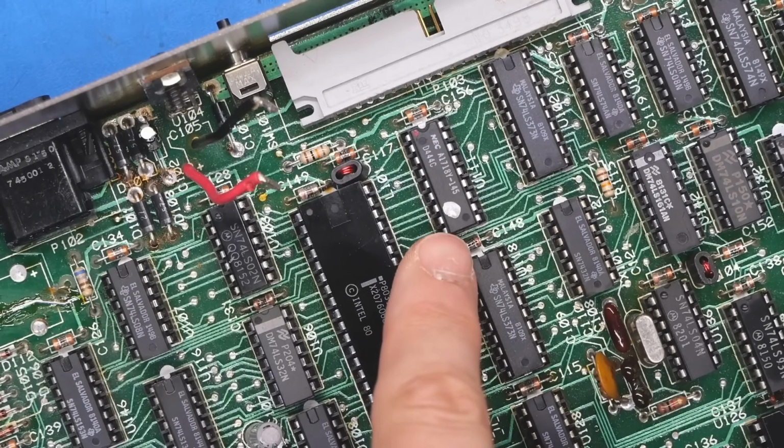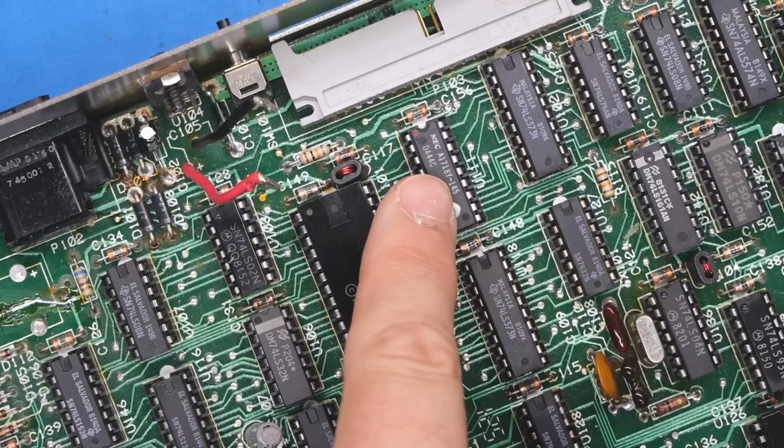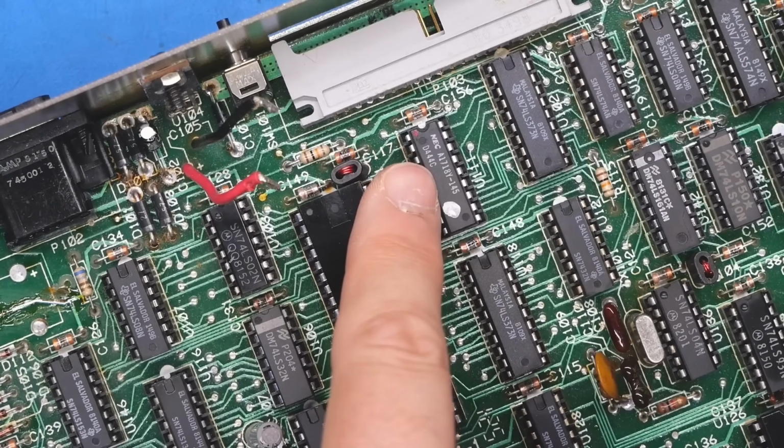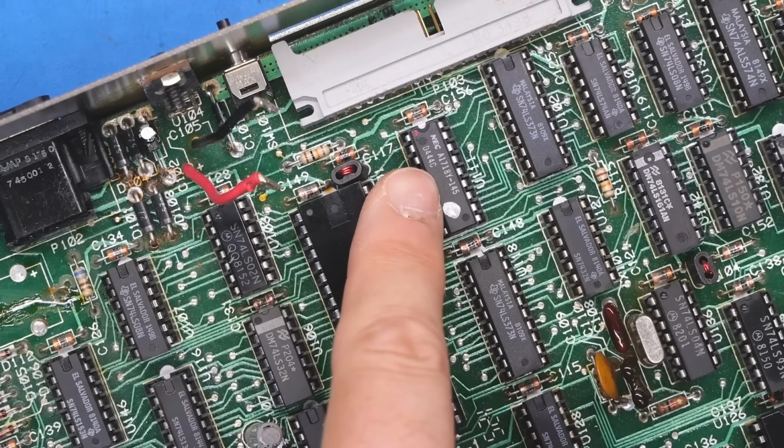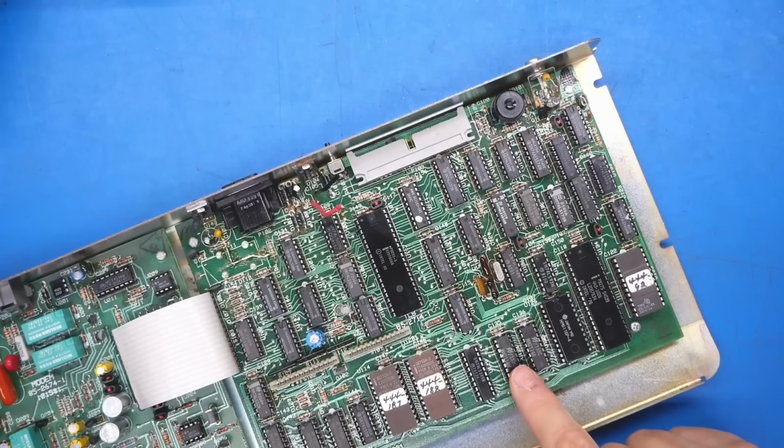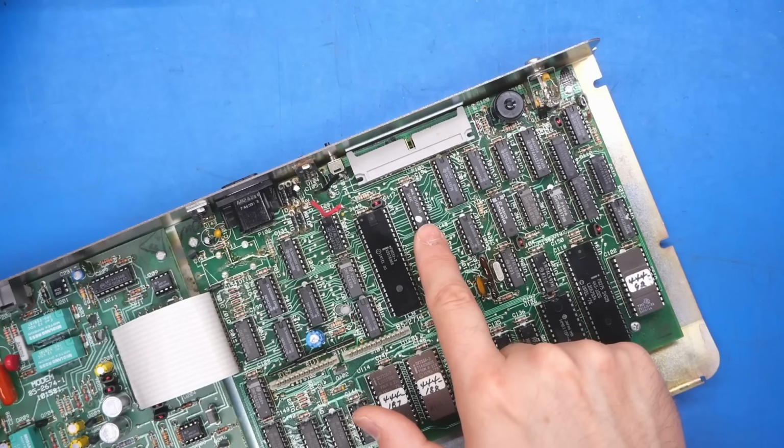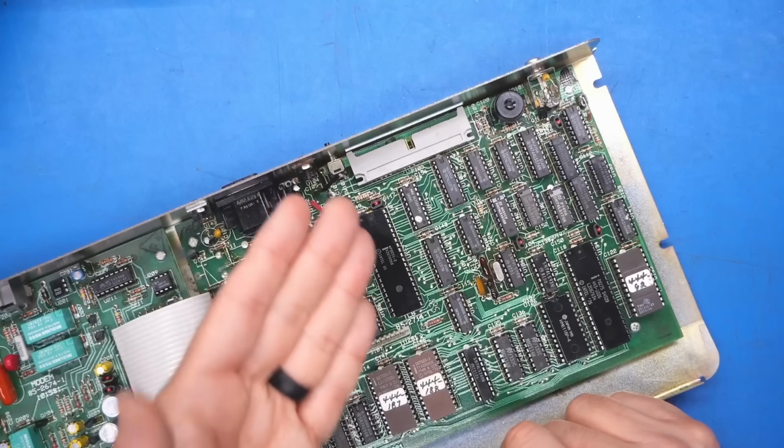It's hard to figure out exactly what part number this is. That top number doesn't really come back to anything, but D444C is similar enough to the NEC U444, which is essentially very similar to these ICs. It's like a 2114 SRAM, so 1 kilobyte times 4 bits, which is plenty of storage for phone book entries.